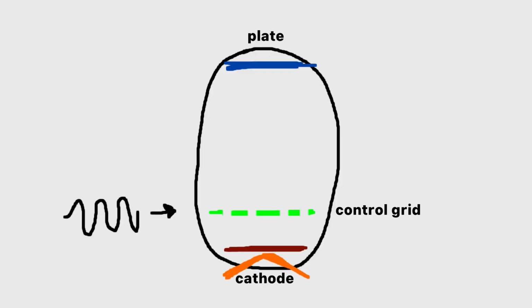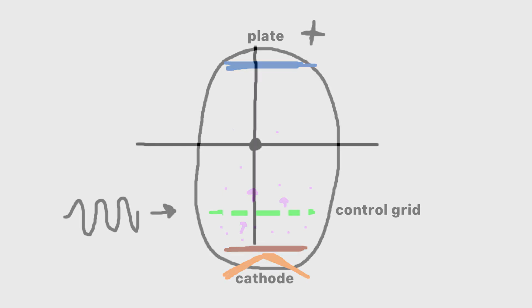If we think now of the control grid as the voltages it contains relative to the plate and electrons, and how it's the positive and negative charges that operate this valve to control the flow of electrons, we can see the unique problem with the negative portion of the signal. As the control grid becomes more negatively charged, it starts to not only restrict flow, but slow down flow as well, until the charge is so great that it repels the electrons altogether. And this has a unique shape as we slow down to that absolute zero clipping point.